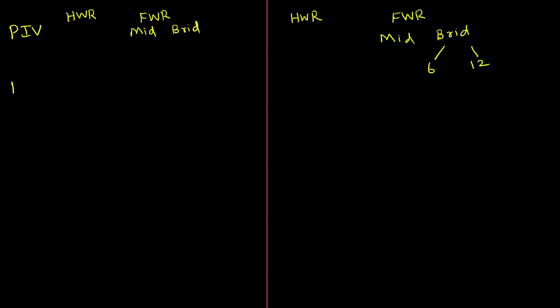I will be writing peak inverse voltage somewhere here. Guys, I cannot bring everything here. I have already told you, the remaining things must be taken care of by you. Okay, sir. So if you take the half wave rectifier, what is the maximum peak inverse voltage that can be blocked by the half wave rectifier? Does any one of you have any basic idea for this? So the maximum voltage blocked by the half wave rectifier is simply Vmax.